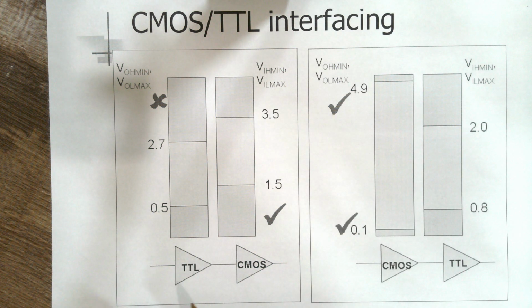So therefore, we cannot drive CMOS technology using TTL. Hence, we cannot connect an output of a TTL to the input of a CMOS technology and expect the circuit to operate properly. Let's look at the other side. Could we drive TTL using CMOS technology?